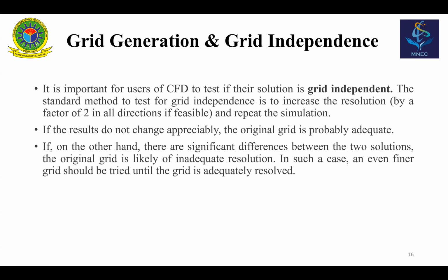So you're quite confused, because with the increasing nodes, your pressure drop value is fluctuating. Then you take 80,000 nodes, and you see that your solution is converging, but the pressure drop value is close to the previous one, that is 30 Pascal.